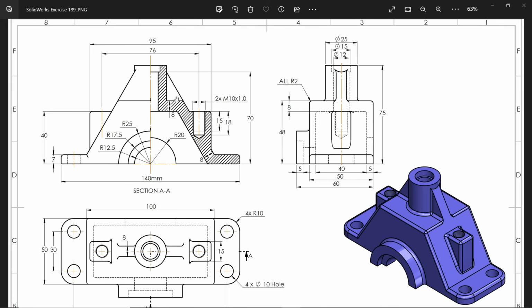This is going to be like here. There is a rib. Before the rib, we have to make this straight body. This height is 48 millimeter. But the problem is there is no angle shown for this taper view. So we will take the help of this rib, 70 millimeter from bottom. See, and this upper pipe diameter you will see here is 25 millimeter. So this is going to attach with this.